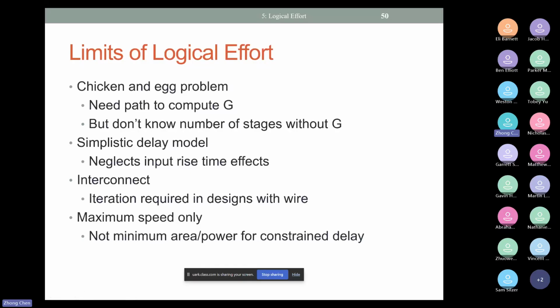When we design it, if you just try to optimize the best delay, you may sacrifice, for example, the layout area, and the power consumption, the standby currents. Because if you increase the number of transistors, it definitely increases the standby current.